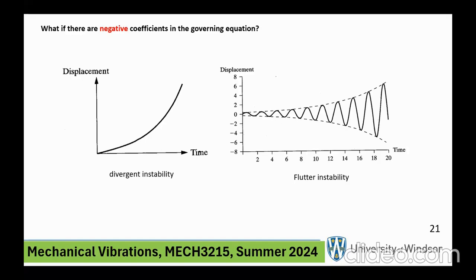Can we have instability in free vibration? In the case of the Tacoma Narrows Bridge, one theory is that the wind flow over the deck caused this harmonic forcing, this periodic force, and the frequency of that forcing happened to match some natural frequency of the structure. That's not what we are talking about here. We don't have any external force.